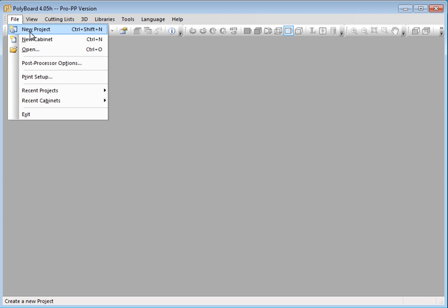When you have multiple cabinets in a project, whether or not you've actually created a 3D layout and positioned them, you can export all your cabinets in one go as a job lot. Whereas if you save it as a new cabinet, then you can export just the cabinet itself. Of course, when opening up a new project, you can also add in cabinets that you've saved separately previously, so that's not a problem either.